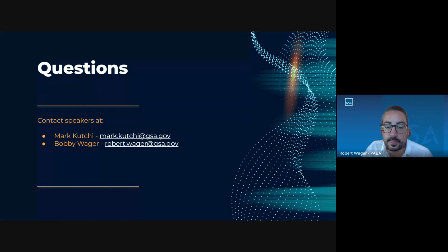Good, Mark. Yeah, I'll just add, Scott, that has come up in a couple of current or recent VRF designs. And I think what we want to point people towards is, if you're using the VRF, then you probably have to move towards the ducted VRF, the concealed unit, where, as Bobby pointed out, it looks and acts more like a fan coil unit versus the cassette type.